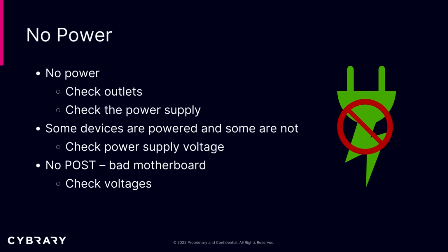No power on your computer. Again, power issues are quite common on PCs. If you have a situation where there's no power at all, of course, the first thing you want to do is check your power source. Check your outlet, check your power supply. Those are the first two big areas that you want to check.